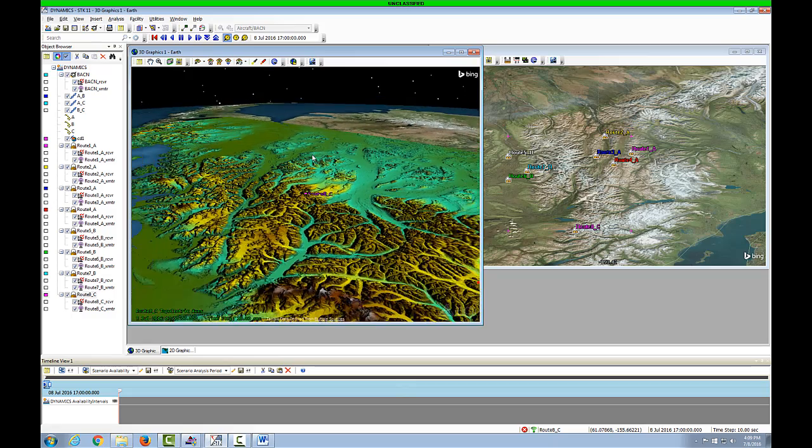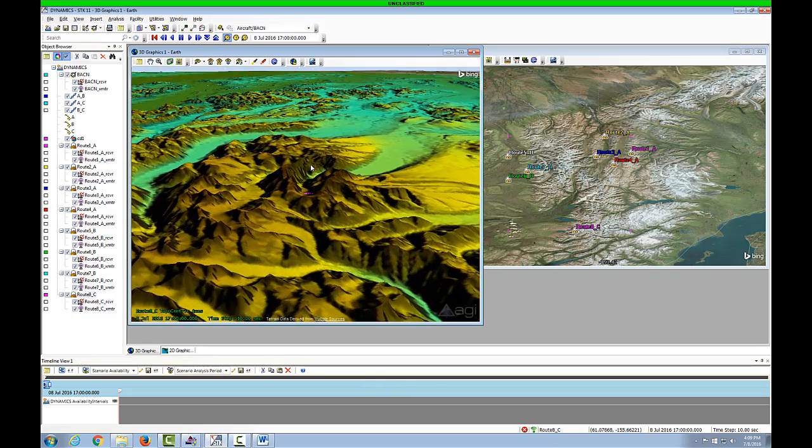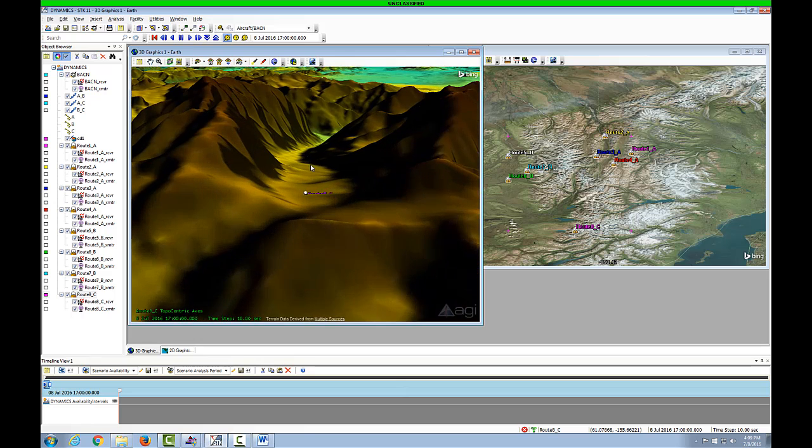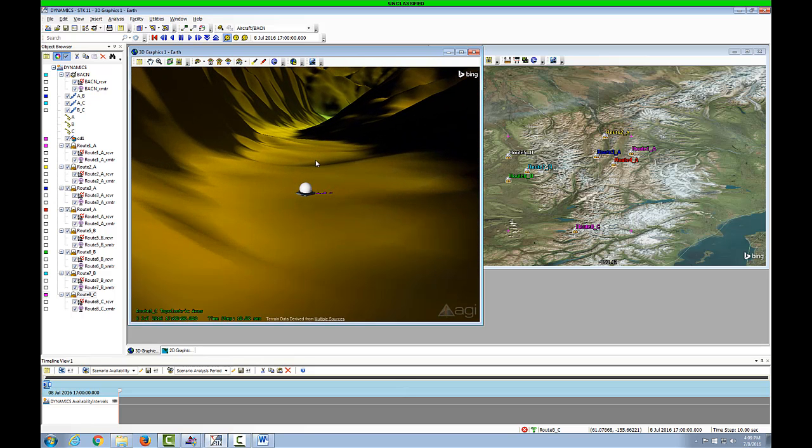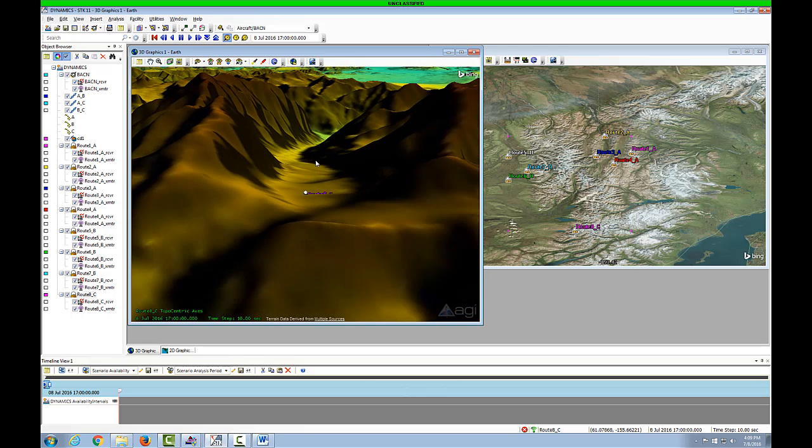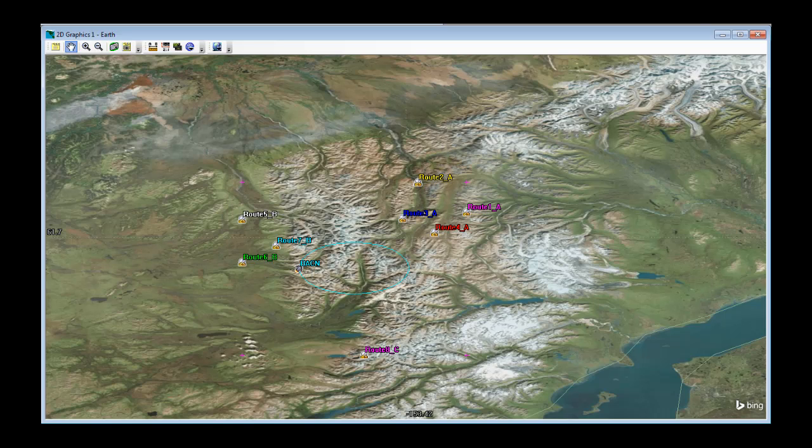We can switch to a 3D view in STK, and you can see that that single node in Group C is situated in a deep valley, which will constrain its ability to communicate with the airborne platform. If we just naively choose an orbit that consists of a circle centered over the entire set of subscribers as shown here, we get poor coverage for our 3 voice bridges.